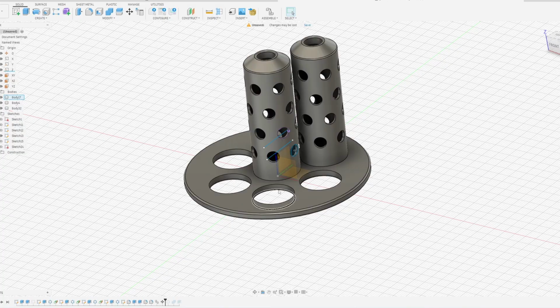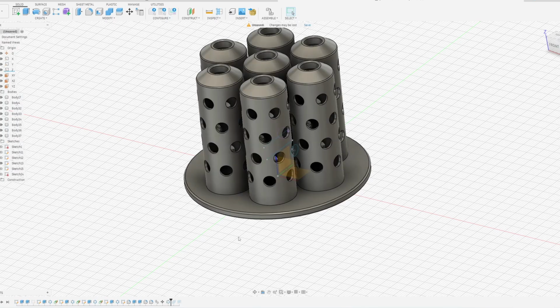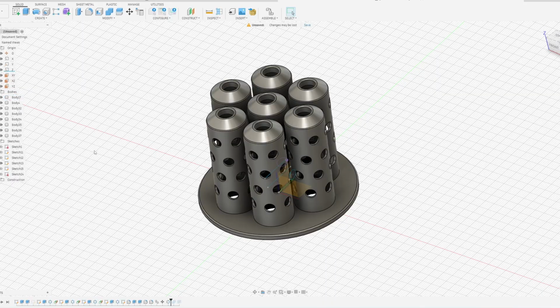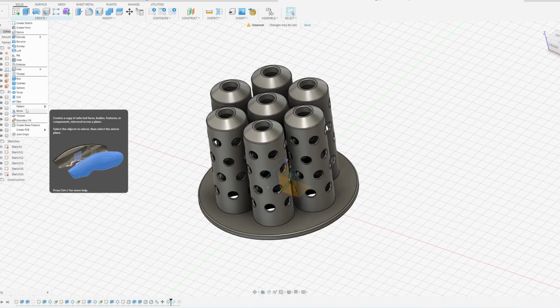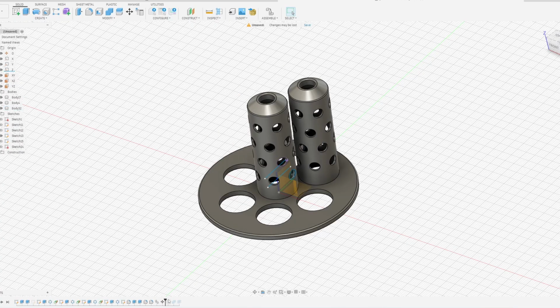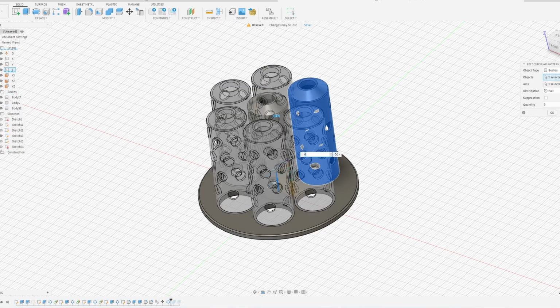use the circular pattern to repeat this feature all around this area. Similar to the circular pattern that you found in the sketch environment, you also have a circular patterning here, and it will move your features, right? So I have this one, and if I click on it, you can see what is copied, how many times, around, fully around, partially around, and around which axis, in this case Z. And click OK.